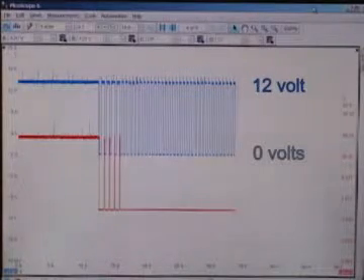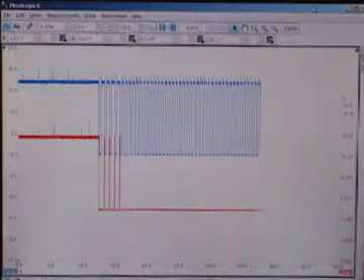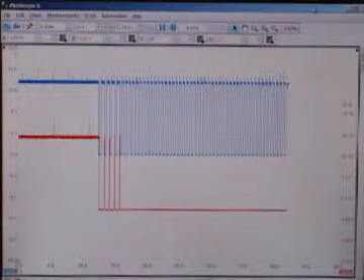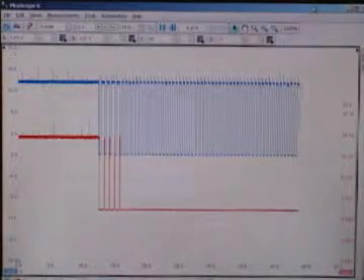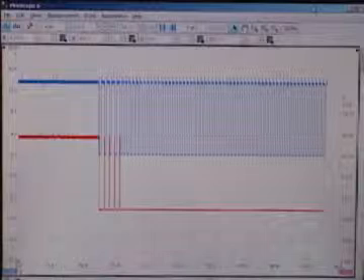This is a ground controlled signal, so the command is the negative slope of the waveform. This duty cycle has a different frequency with 3 stages as to initially determine a large, medium, or small leak, and may be repeated as many as 3 times.